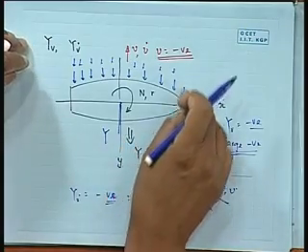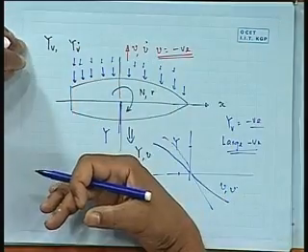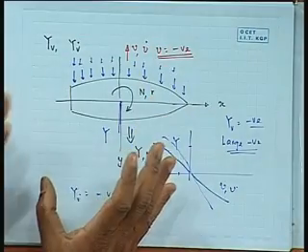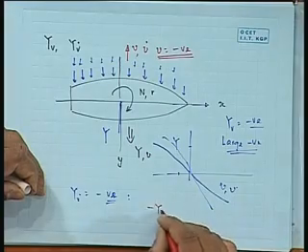So you can say that the fluid is trying to get accelerated on that side, which will give you an inertia for the opposite side. Because if I took this body and tried to accelerate it in the negative direction, then I get a mass into acceleration force in the negative direction. So that is why I get minus Yv dot v dot. I get a force of minus Yv dot v dot.